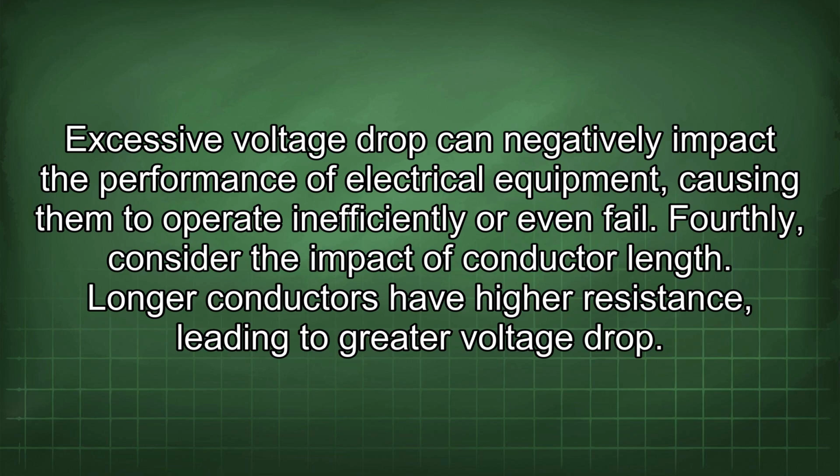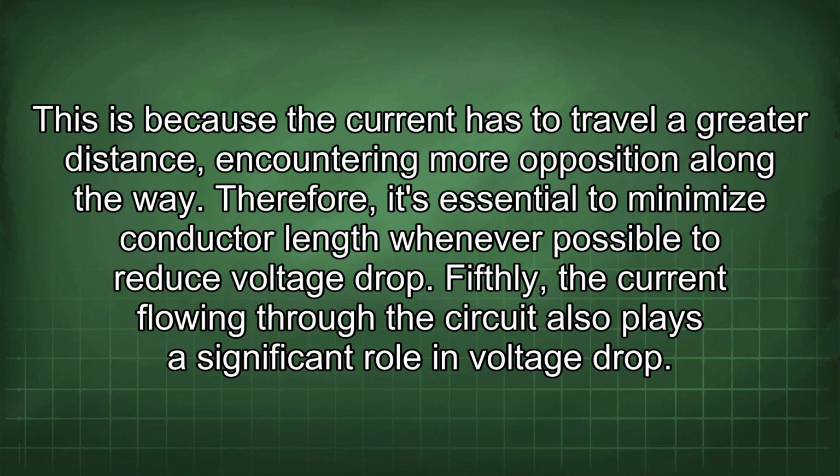Fourthly, consider the impact of conductor length. Longer conductors have higher resistance, leading to greater voltage drop. This is because the current has to travel a greater distance, encountering more opposition along the way. Therefore, it's essential to minimize conductor length whenever possible to reduce voltage drop.